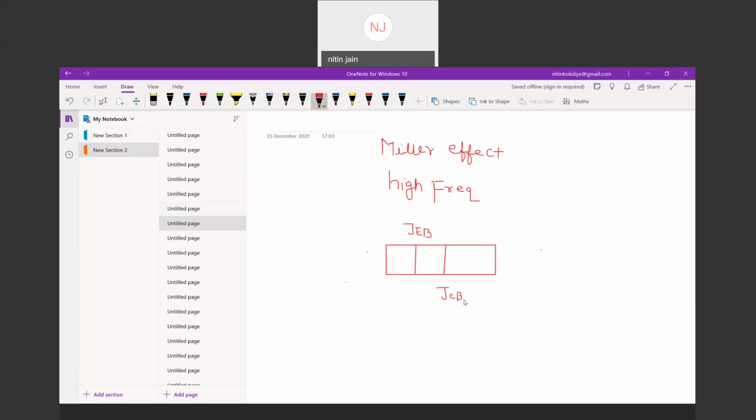So you can say two charge carrier plates are isolated by a dielectric. So this will form a capacitor. The one capacitor is known as C pi, which is this junction capacitor. इस junction का जो भी capacitor होगा, that capacitor acts as C pi, and another capacitor is C mu. The C mu is capacitance at collector base junction, and C pi is the capacitor at emitter base junction.